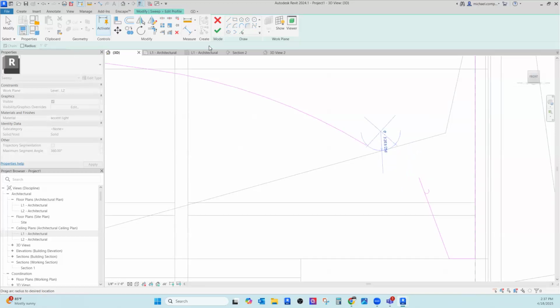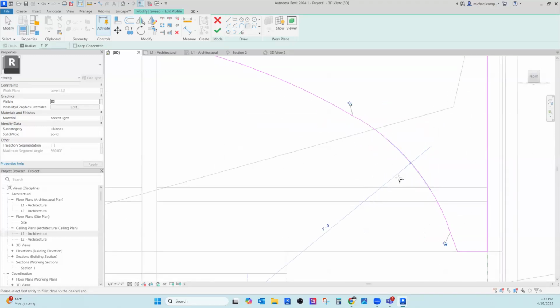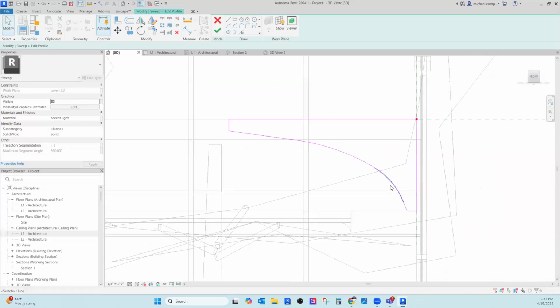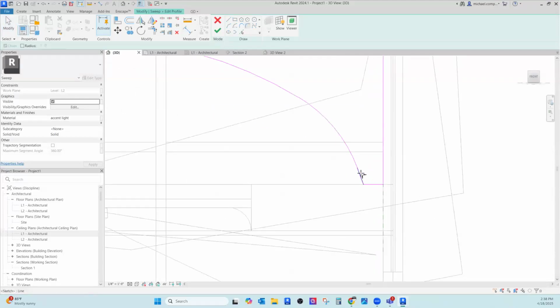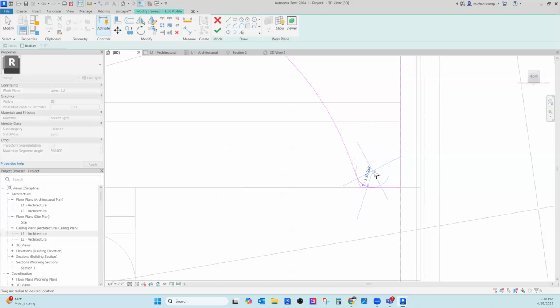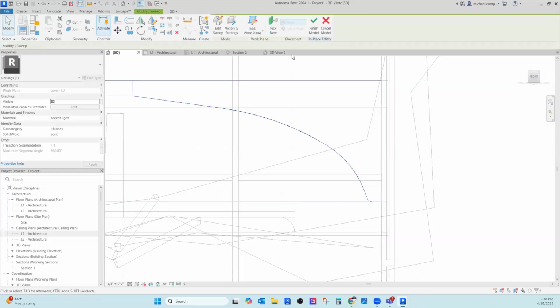So sometimes you have to put in a dimension, like a radius, because you can't eyeball it all the time. So like that one now, but I want it to be 3 feet. There we go. That's better. Right. So it's not a simple arc, but it's a 2-part arc. And actually, I don't know if you'll see this, but I want this to be coved also, or curved also. So now we're getting the Zaha level of curvy bits, which is okay. And hit finish, hit finish.